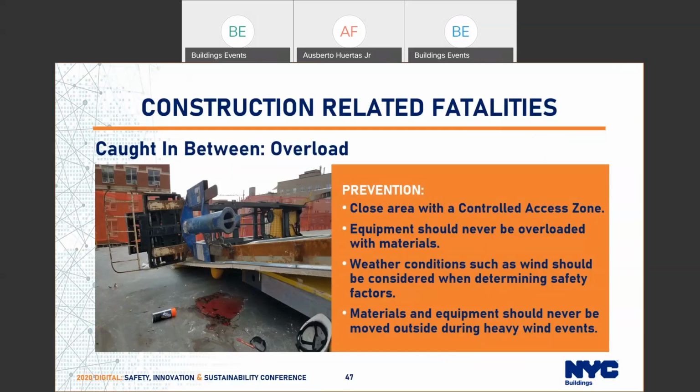events. Always check load capacities of the equipment that will be utilized. Remember, the forklift was rated at only 965 pounds and the panel weighed over 1,200 pounds, not including the force of the winds. That is an overload that should not have happened and should have been avoided.